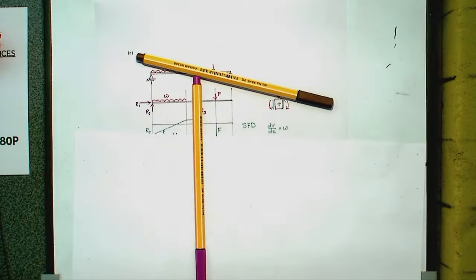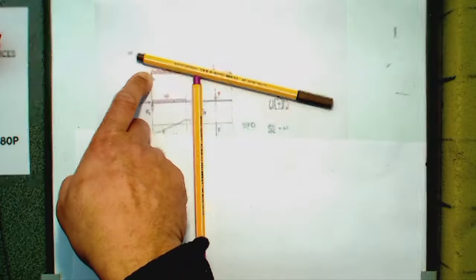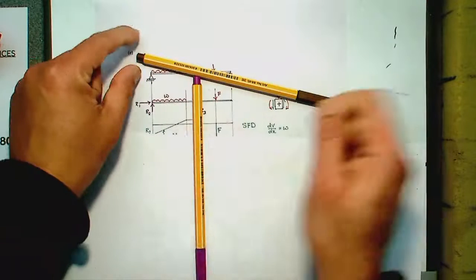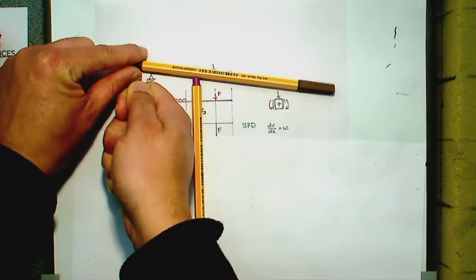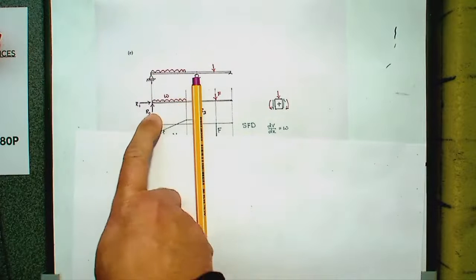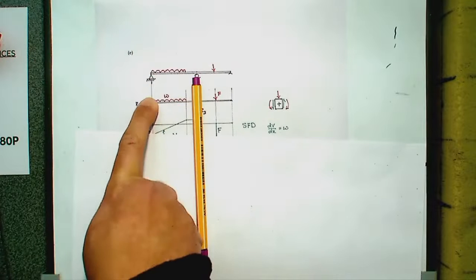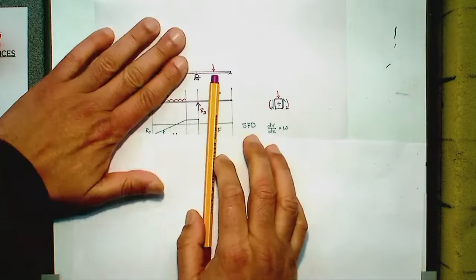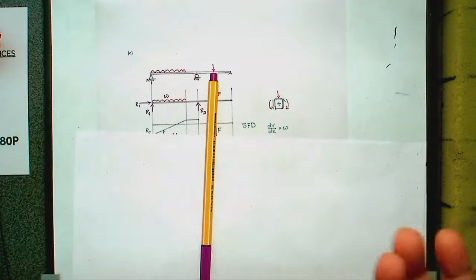If it goes up like this, of course this point is connected to the ground by this pin. It cannot just move up. So what does the pin do? The pin will try to pull it down towards the ground level, so you'll have a reaction force coming downward. Yeah, so the two loads I'm considering separately, for the effect on the reaction force.